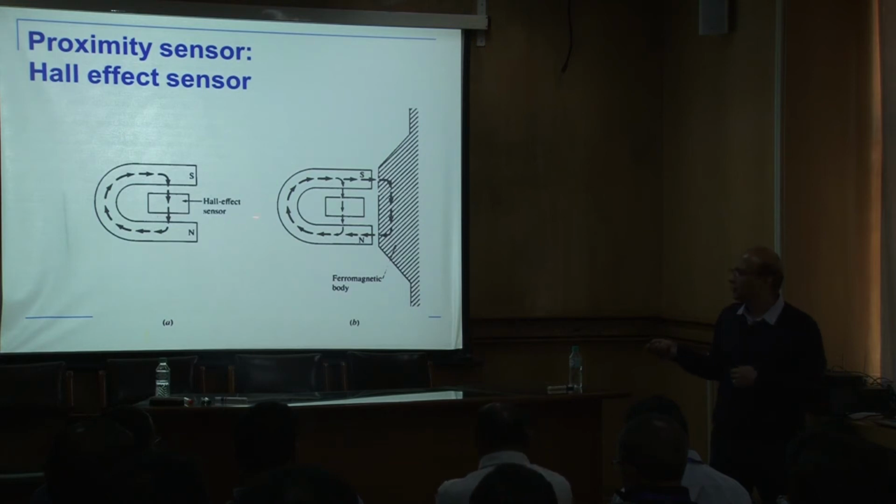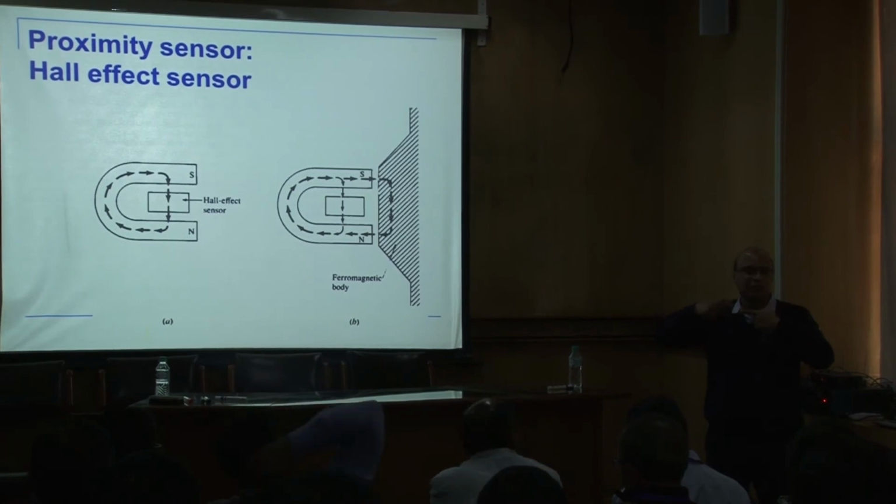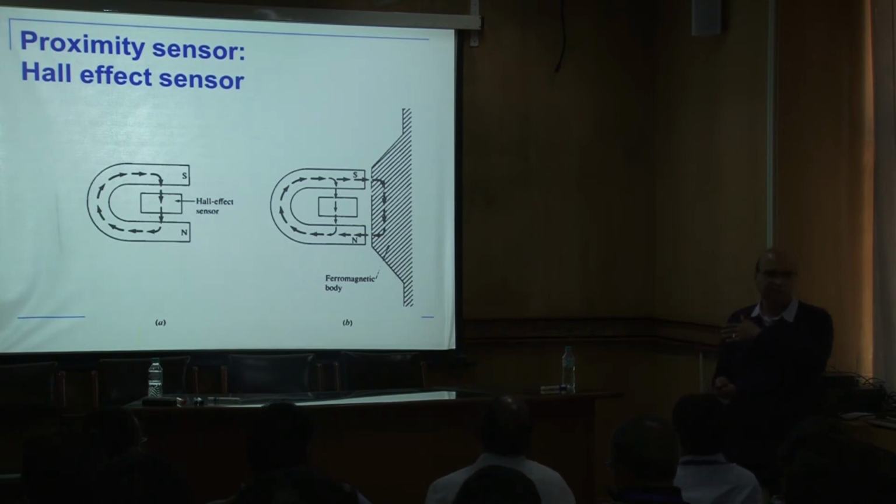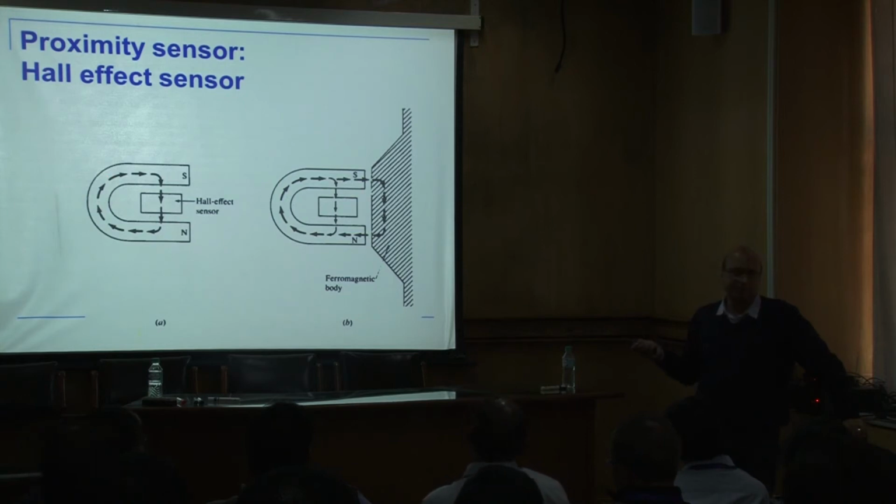So at the output of the engine, on the shaft, there is a small projection, something like this. Depending on how fast it is rotating, how many times that projection comes by, from that it knows how many times it has gone round. So there is the counter. There is engine RPM. Now the wheel RPM is after the gearbox, right? So this sensor is also used for measuring the car speed. So in robotics, we can use it for measuring distance, proximity, but it is also used extensively in other applications.